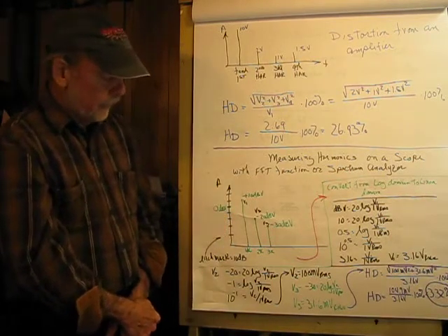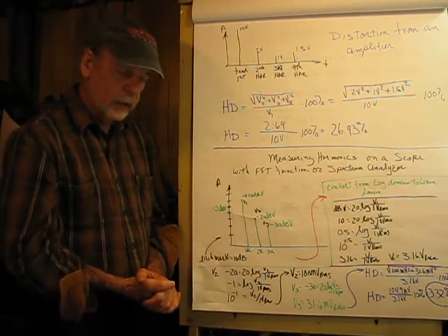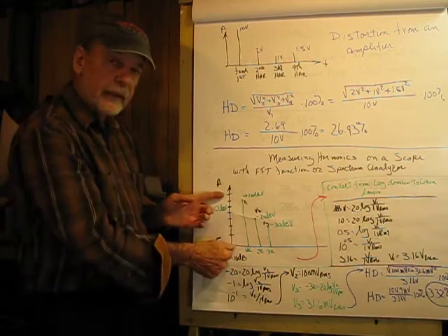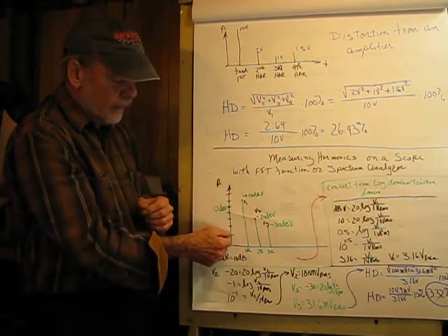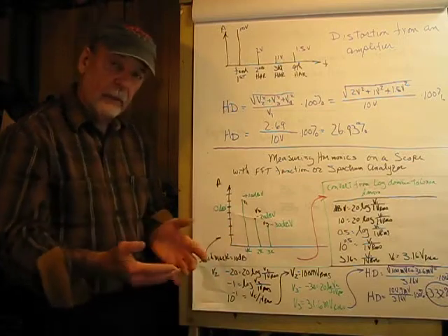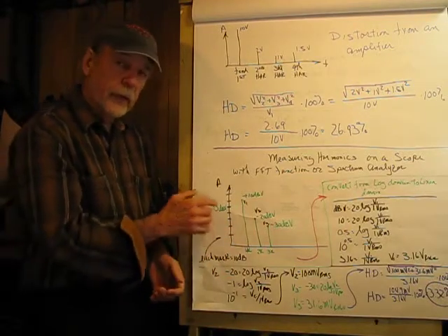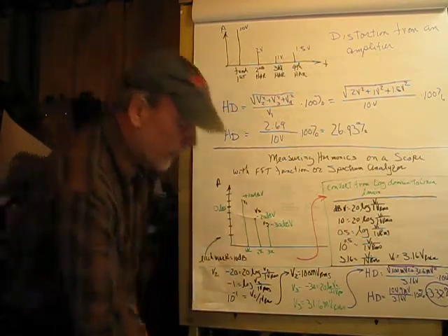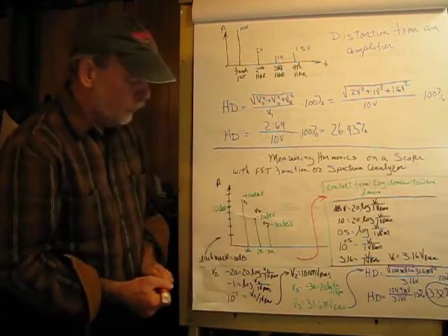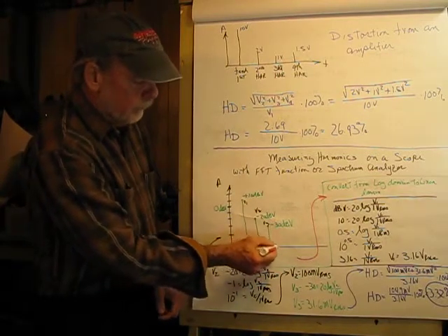Now, you might think that that's kind of an unnecessary thing to do, but the dynamic range of what it can display is enormous. Plus, you can scale this down where each centimeter could be, say, 5 dB or 2 dB to make a very granular measurement. So typically what sits down here is the noise floor. Kind of looks like this, actually.